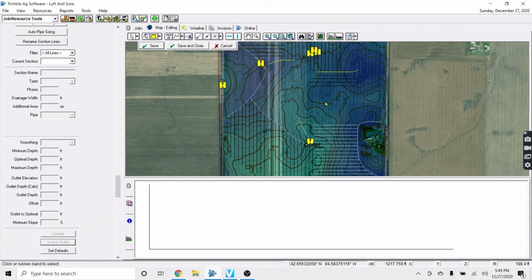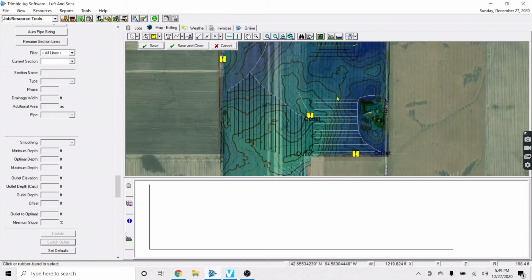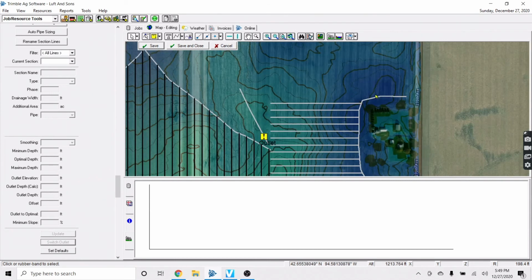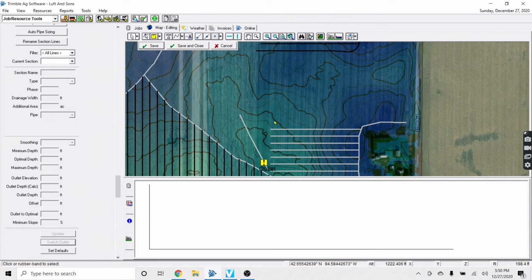to decide. We can take the water both directions at this point. So if we zoom out a little bit, this area here can go this way or it can go this way. And to decide where you're going to take it then, first and foremost, you want to know where the better outlet is. So sometimes you need to ask that with the locate crew or the farmer, or one of us might know. But at this point, you have to realize we're already going through overcut here. This is a grounded out wet spot. I don't know if we want to bring all that water down there.